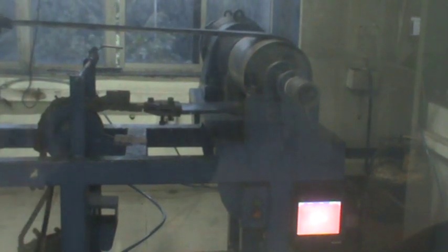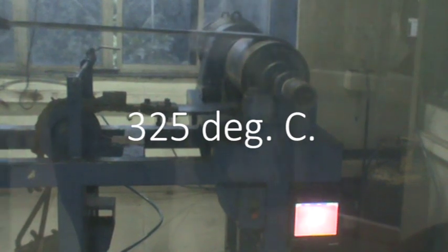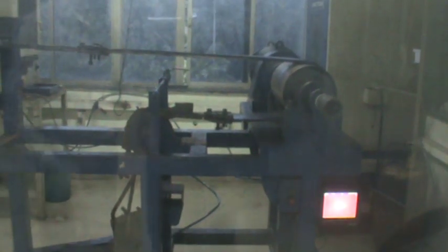In the case of AS 4606, the maximum temperature allowed is 325 degrees Celsius. Testing is usually conducted on the top cover and then also on the bottom cover. In addition, the testing is conducted once using a jet to blow compressed air onto a belt to simulate a draft which may be present in mining shafts. Therefore, testing is specified as being with or without air.